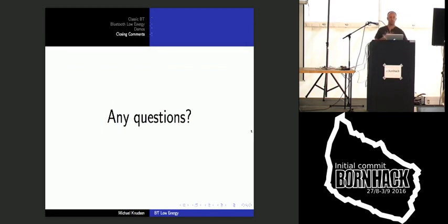You didn't talk about pairing, so is that handled in another layer? Yes. The question is about pairing. In classic Bluetooth, pairing is done using link level commands, but in LE, this is done using a higher level command. So you establish a connection and you send data packets back and forth saying, I would like to do a pairing with you.